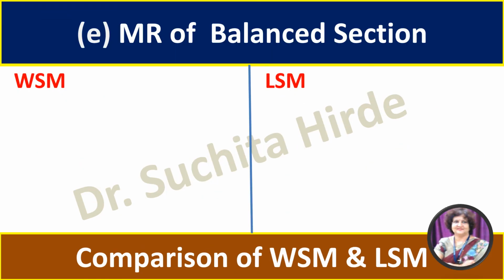Next point of comparison is moment of resistance of balance section. We need this moment of resistance of balance section while designing the section. While designing RCC section, we equate moment of resistance to external bending moment due to load. So to decide the size of the section, we have to calculate the moment of resistance.